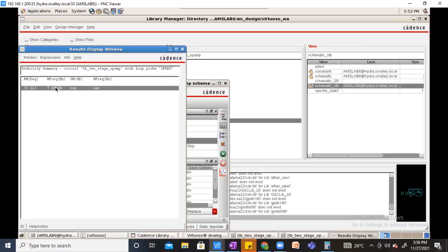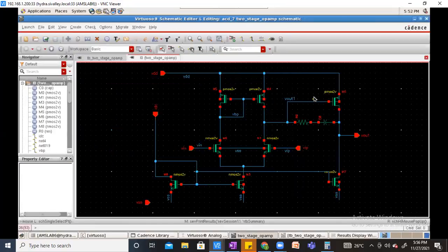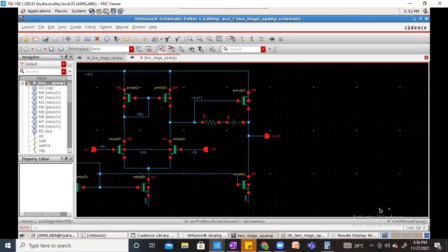Okay. It's very simple, right? When you close the input to the output, if you take just a simple common source amplifier only, okay. Let's see, if I take common source, this is the common source amplifier. Consider only this part. Okay. If I short these two, and without shorting these two, you can see the total resistance at this point will vary, which means that the pole location will be at a different point. If I short, the pole location will be at a different point, right?